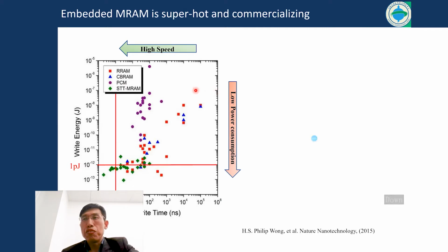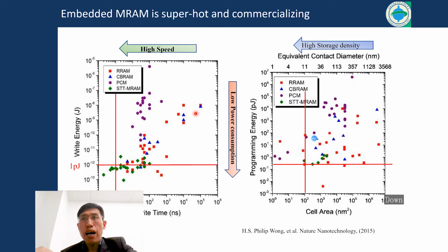So for the first time, STT-MRAM provides a perspective over resistive RAM and phase change memory, 1 nanosecond for the switching, and 1 picojoule for each bit switching. The fast speed and ultra low power enable its application for embedded solutions and computing systems.